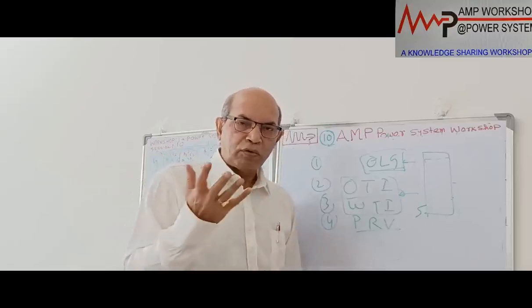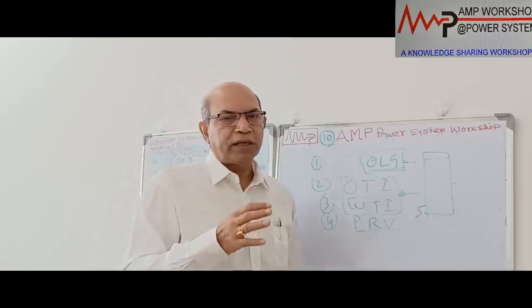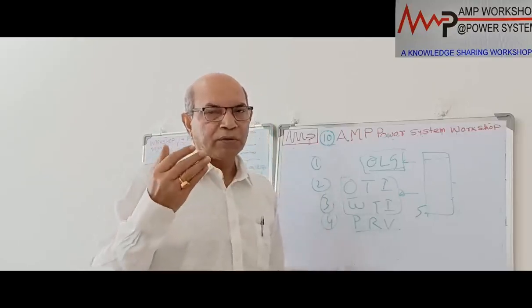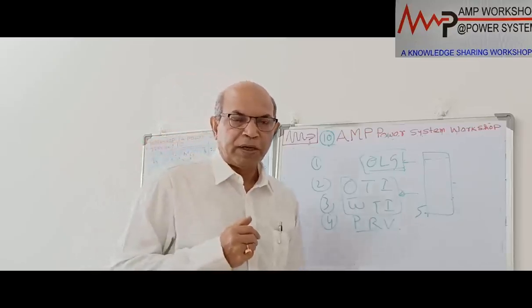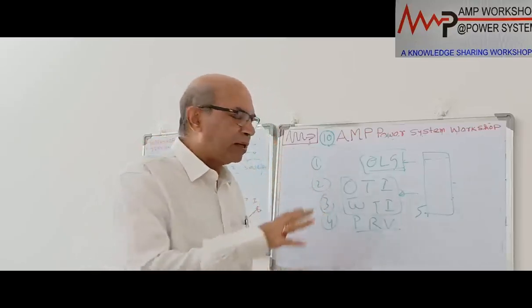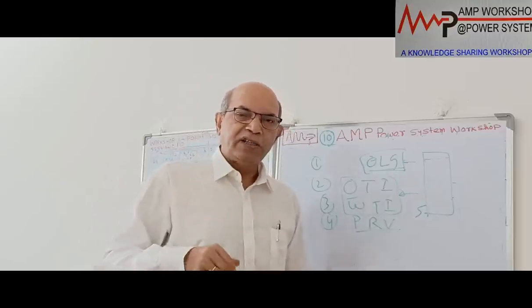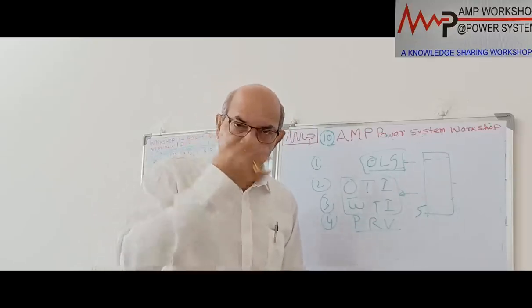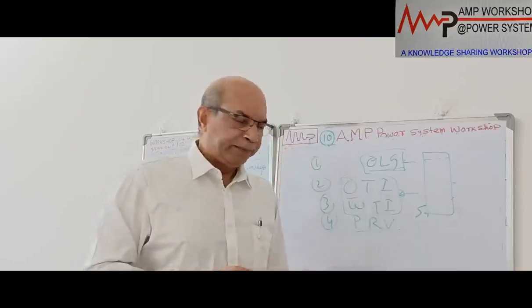So it has two contacts, one is the alarm contact and another is the trip contact. So we can set the contacts in such a way that if the winding temperature comes to 105 degree, it will give an alarm, and at 110 degree, it will give a trip. This oil and winding temperature will rise when the transformer is getting overloaded, or if there is an interturn fault, or a phase fault inside the winding. All this will be protected by the oil temperature and winding temperature indicators.